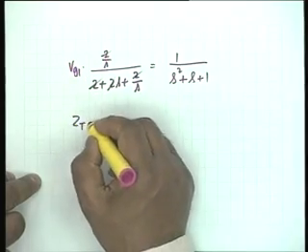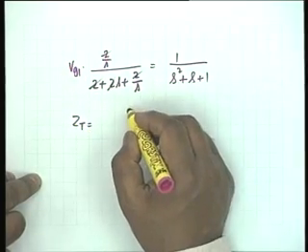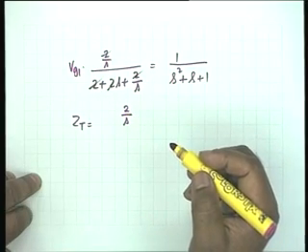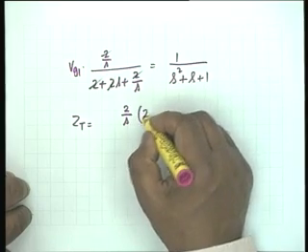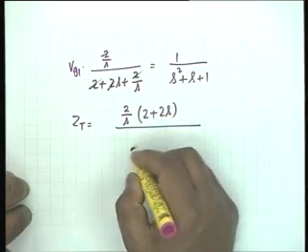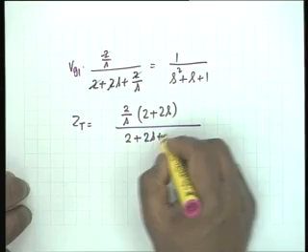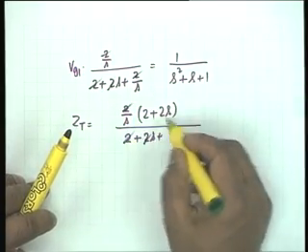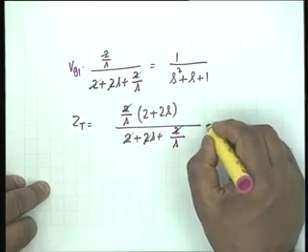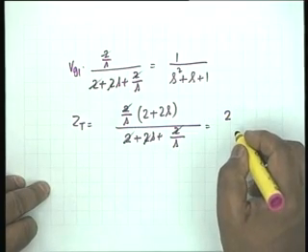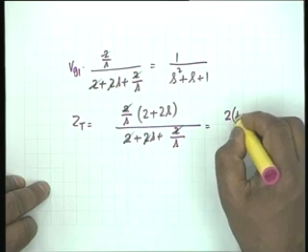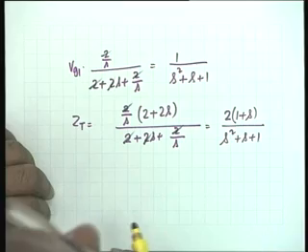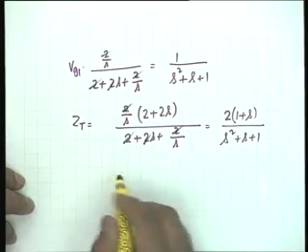And the Thevenin impedance ZT is half farad, that is 2 by S in parallel with 2 plus 2S. So, 2 plus 2S divided by 2 plus 2S plus 2 by S, and once again you can forget about this 2. So, you will get 2 into 1 plus S divided by S squared plus S plus 1. Alright. So, our equivalent